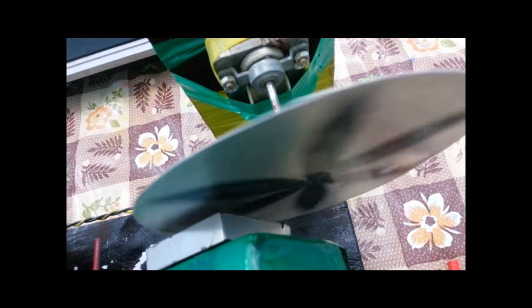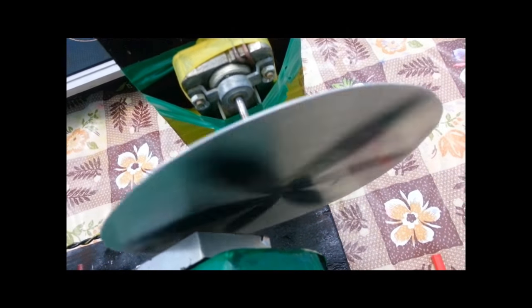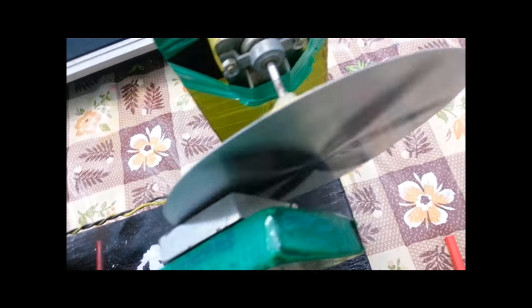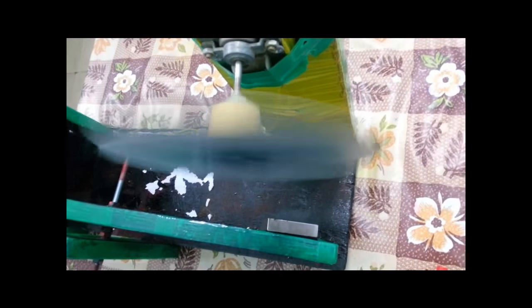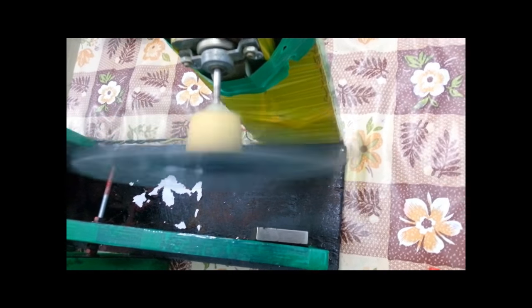And the advantage of this power brake system is that here the disc and magnet do not come in direct contact, so there is no problem of friction or wear and tear. There is no need to change the brake shoe frequently in the case of a power brake system, because there is no role of friction in this case, and the disc is stopped only because of the opposite torque experienced due to the eddy current flowing through it.